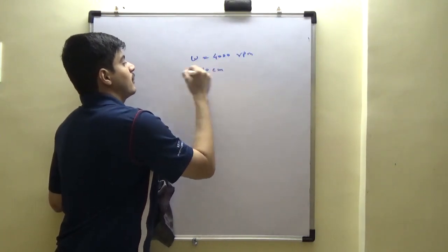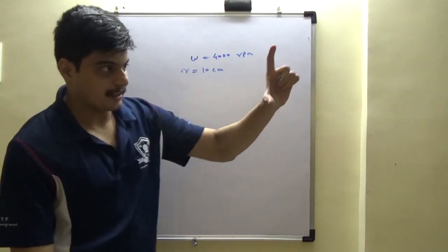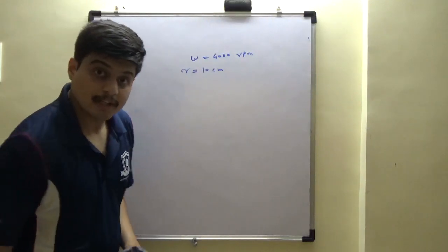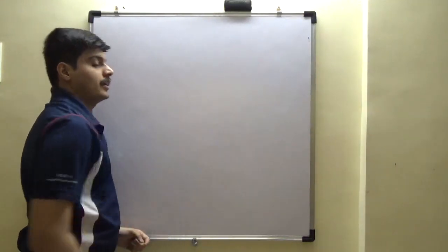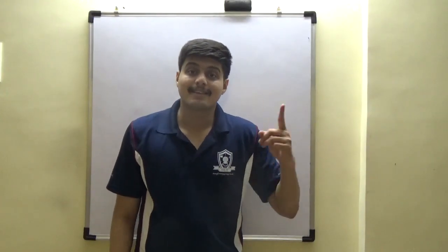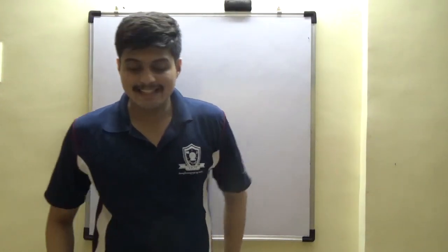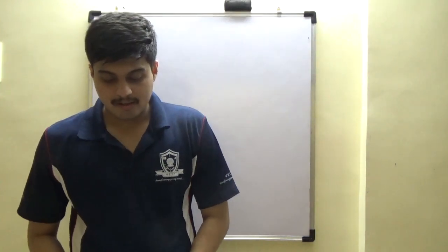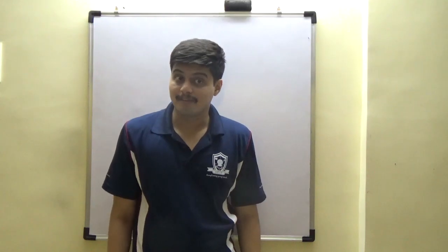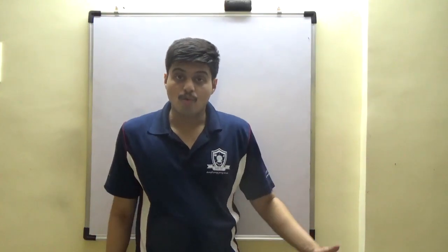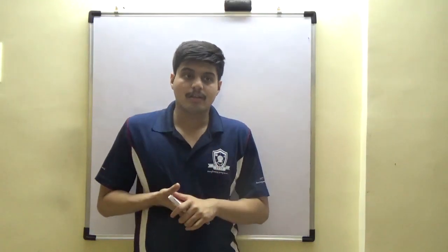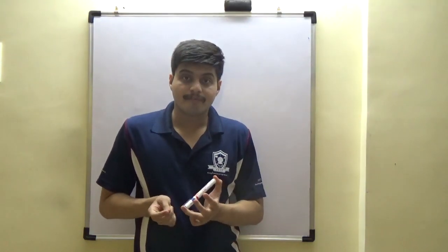And a 10 centimeter radius, which is typically the blade height, means the speed is very, very high. It is the single stator-rotor combination that makes the difference. The Cz that you saw was 160, a very high axial velocity. So just having one stage is not enough.